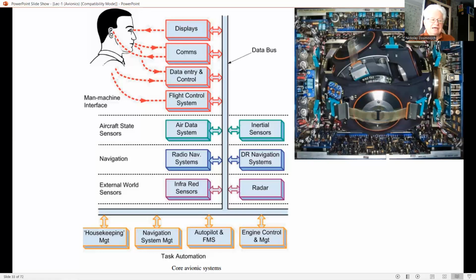This information is essential for the control and navigation of the aircraft. The air data computing system computes these quantities from the outputs of very accurate sensors, which measure the static pressure, total pressure, and the outside air temperature. The airstream incidence angle is derived from airstream incidence sensors.